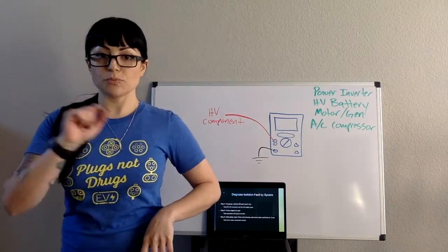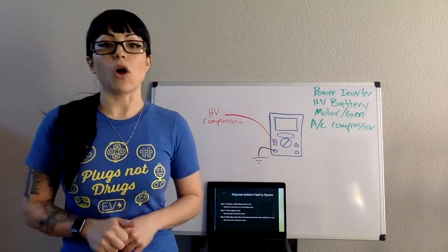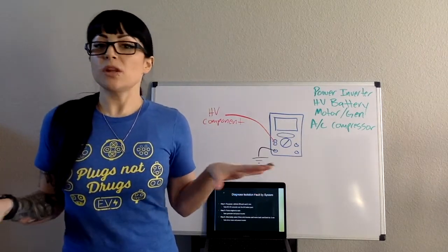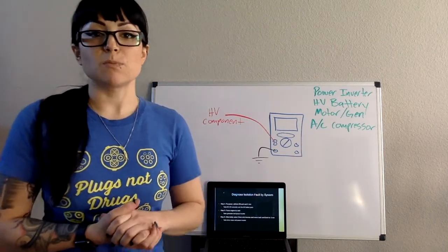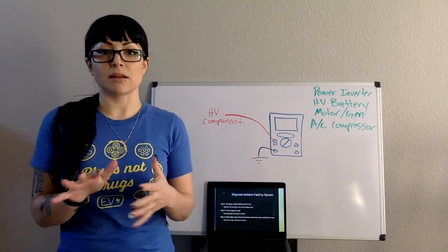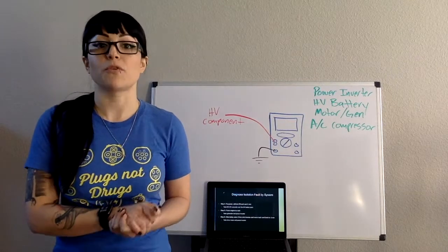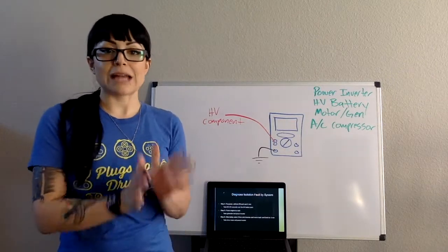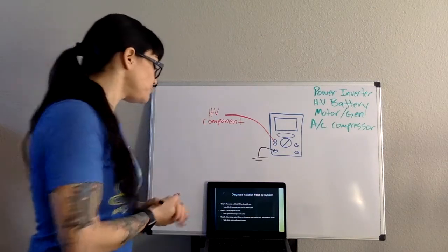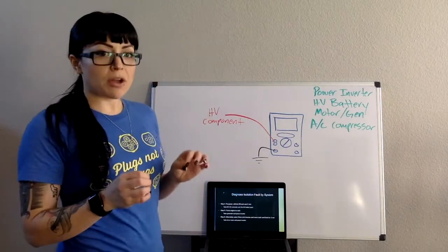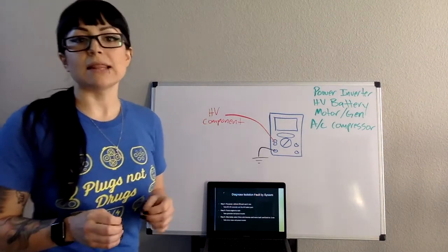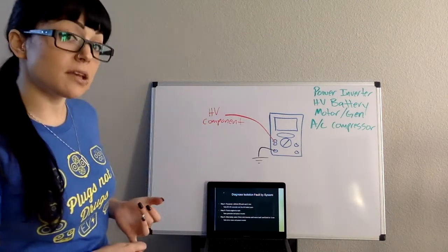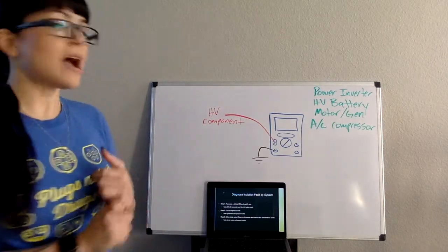So all you're going to do is put on the brake, power the vehicle on, and not do anything else. Each one of these steps is going to require 2 minutes, because sometimes it takes a little while for that isolation fault to happen or for the code to pop on. So we want to give it at least 2 minutes so we know it's not that system that we're worried about. Just powering on the vehicle from the start allows us to identify if it is a DC to DC converter problem or a high voltage battery pack.